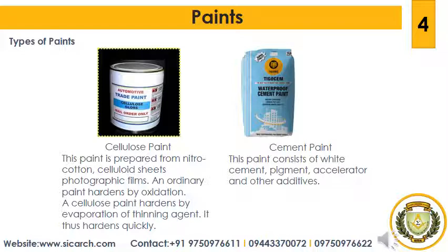So it requires less skill and time for applying cement mortar paints, and applying implements can be cleaned with water only. The preparation of surfaces is easier in a cement paint system as it is not necessary to remove the previous coats of cement paint. They are suitable for painting fresh plasters having a high alkalinity because cement paints are not likely to be attacked by the alkalinity of masonry surfaces. So they become an integral part of the substrata and to its strength.